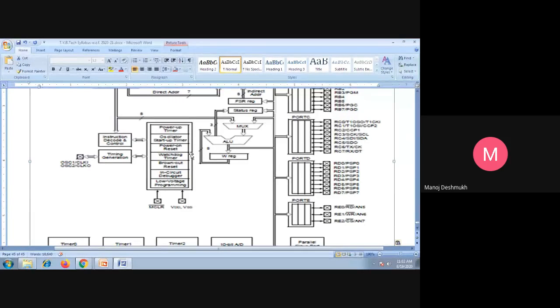So just we have seen the lower side, that is reduction less than 2, and this is applicable also for the higher side, that is if it is greater than 5.5. In that case, after tolerance, it will not be susceptible to the controller, so it will again reset your controller. So this is related to the brownout reset circuit, which is the most important additional facility provided as a protection circuit to the PIC microcontrollers.